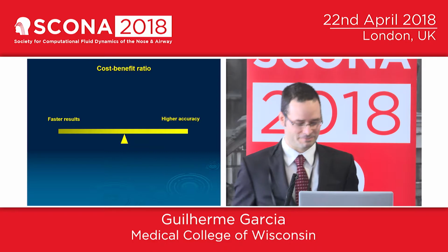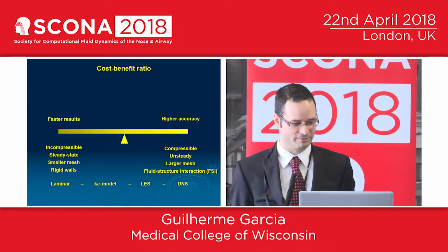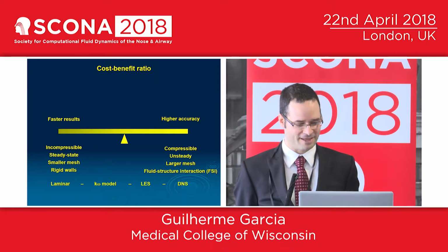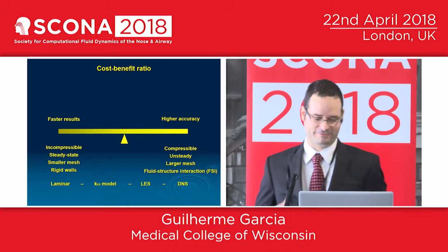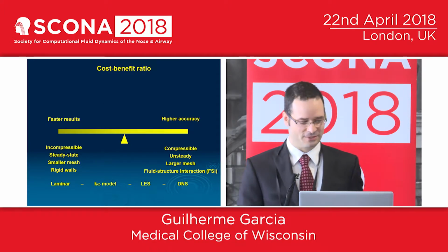To help with our thinking, I'm proposing this framework: I think there is a cost-benefit ratio. If we make assumptions of incompressible flow, steady flow, small meshes, we can get faster results. Of course, we can get higher accuracy with unsteady flow, like direct numerical simulations and so on.